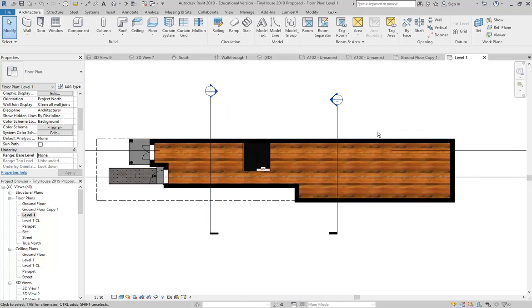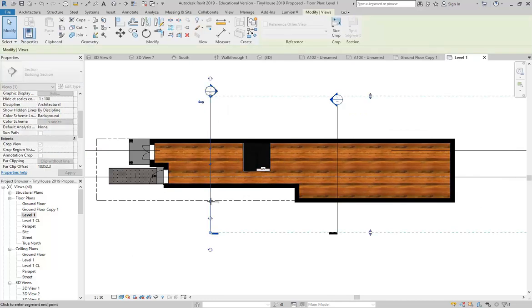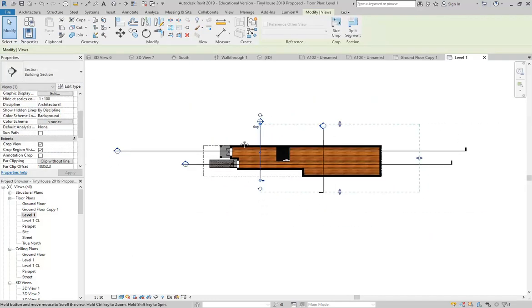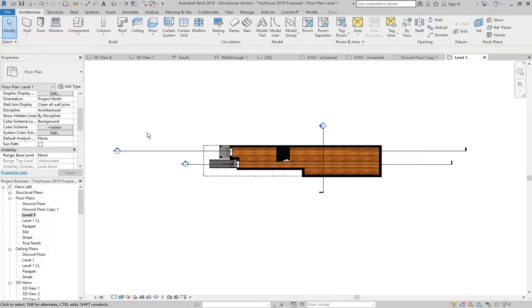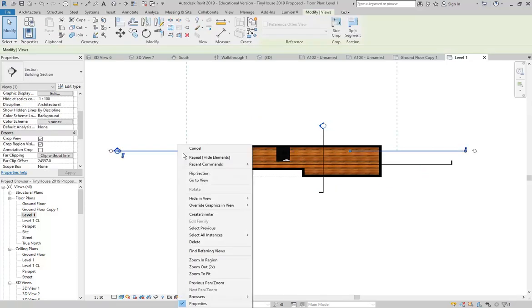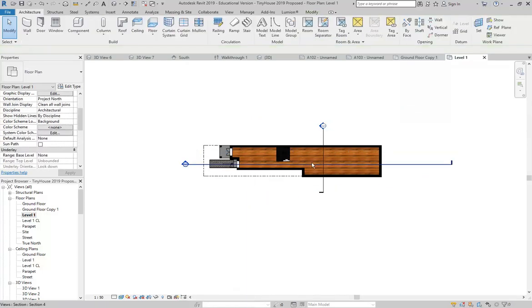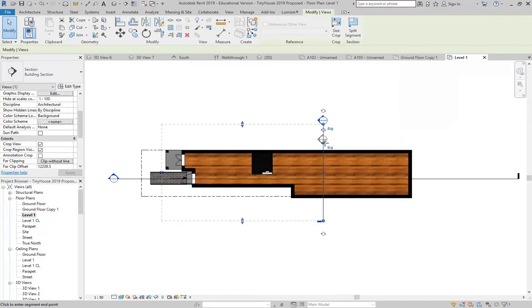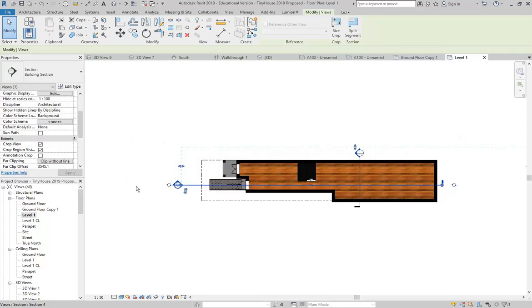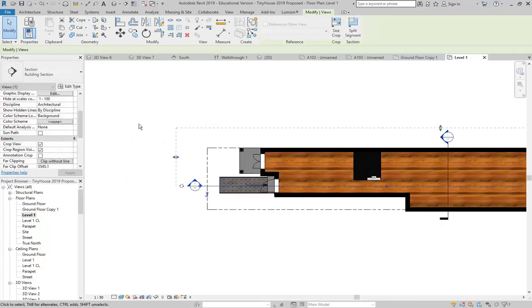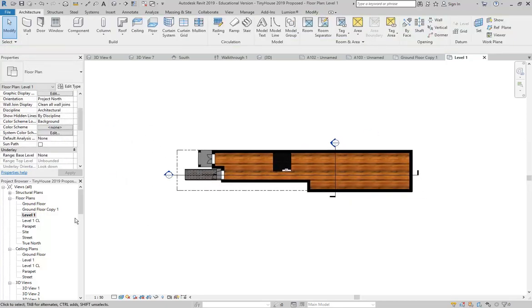So I don't have much on this level, but it's enough to show you how to put it on a sheet. So again, the sections need to be hidden individually because they were hidden by element, not by category. So the things hidden by category have come from the ground floor, but not the things hidden by element, because that's a unique view setting. So all of that little adjustment that you make to the views can then help a lot when you...